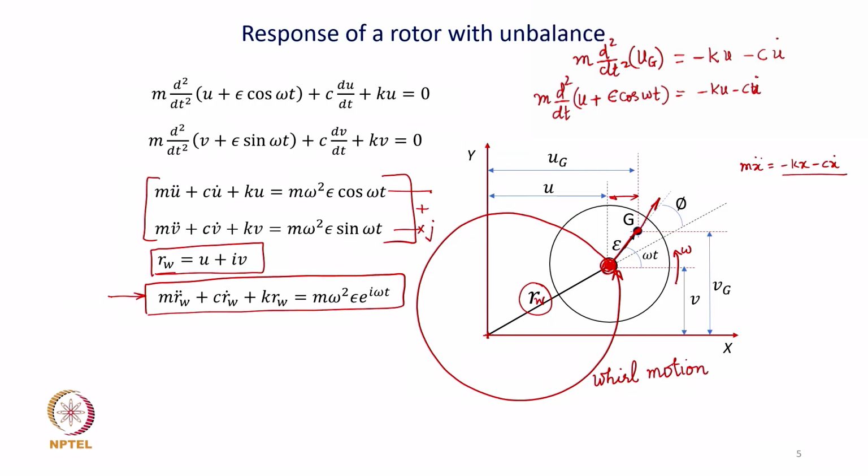But when that stretched shaft orbits around the bearing axis, that whirl motion is the vibration. Spinning is different, vibration is the whirl motion, and the combined vertical and horizontal vibrations together trace out a whirl orbit about the bearing axis, which is here.